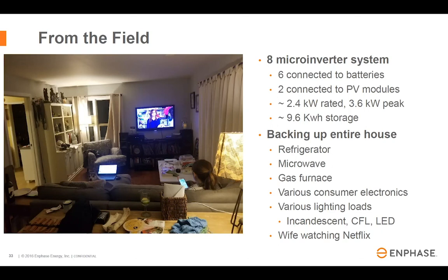Excellent presentation, thank you. So first off, your wife's behavior in the protection industry is called a trip flag, a big LED that says you just tripped. So I'm trying to figure out the marginal cost of her comfort level so that I can bid that into the system. That's awesome. So the next clarification would be that the X over R ratios are most commonly used to determine the breaker sizing, because what you're looking at there is DC offsets and ring down. Thirdly, the X, the impedance, is most important from their perspective for time coordination. So there are different reasons they're asking for X over R versus X. Mm-hmm. But otherwise, wonderful.